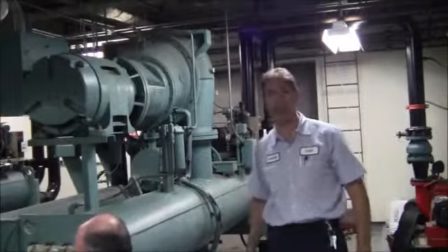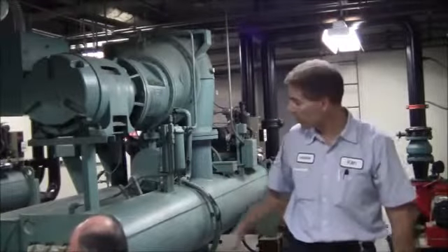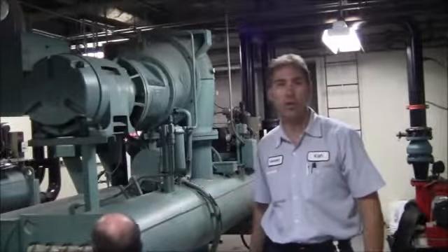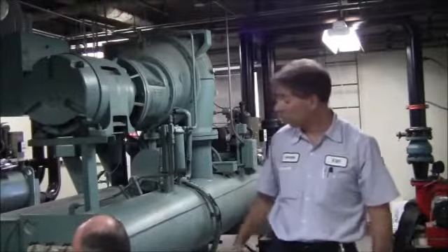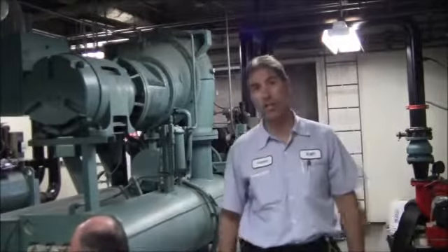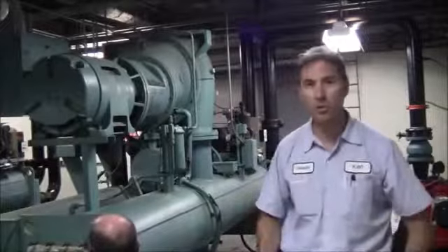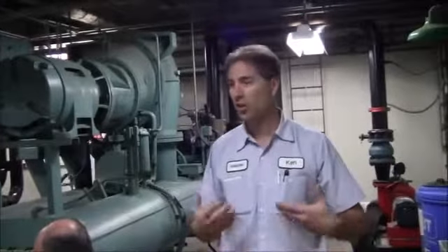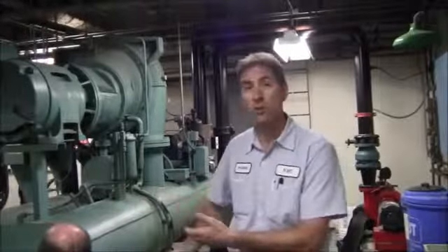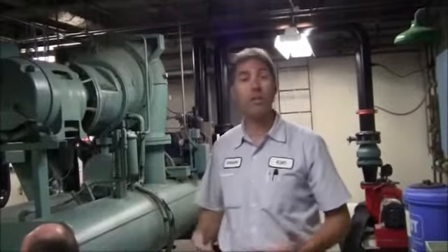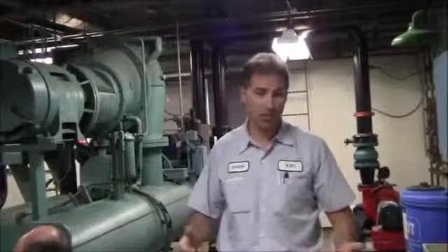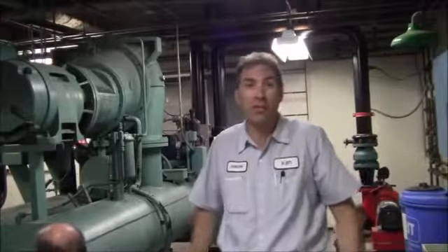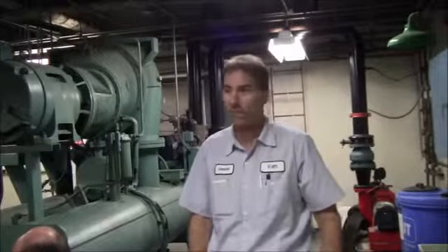This particular chiller, which runs R11 refrigerant, is a little over 26 years of age. So we're performing an eddy current test here to see how the tubes are doing at 26 years of age. How many more years can we get out of these tubes and out of this chiller? And what is the life expectancy of the chiller? Some people say life expectancy is 25 years, so we're already at that life expectancy. But you can push that out with good maintenance and repairs and so forth.